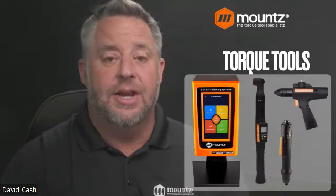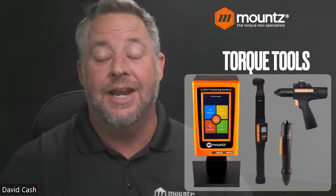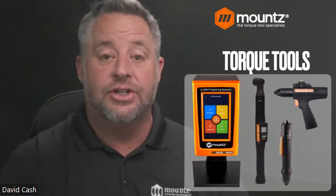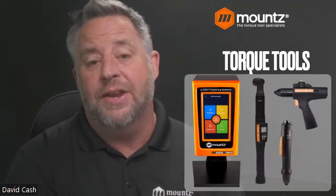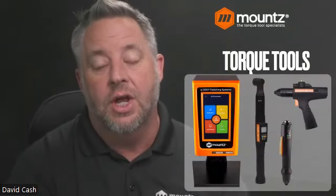They give us the ability to have multiple different presets that we can use within a specific range of a particular tool. And they come in different types of configurations, from right angle tools to inline tools, and also pistol grip style tools. But the real big advantage to the DC tool is control.